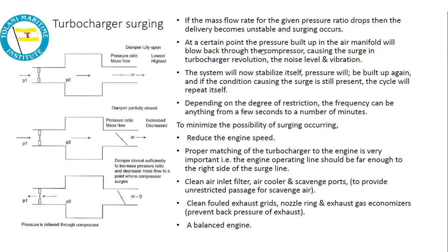At a certain point, the pressure built up in the air manifold blows back through the compressor, causing a surge in the turbocharger revolution, noise and vibration. The system will then stabilize itself, pressure will build up again, and if the condition causing the surge is still present, the cycle will repeat itself.